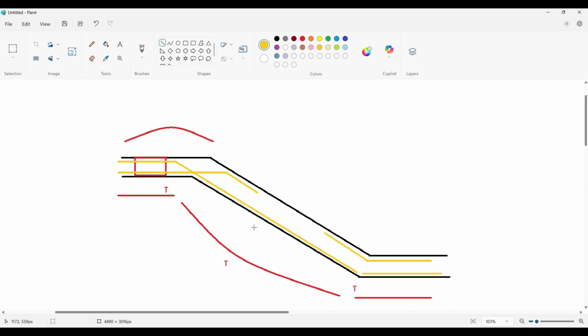Okay, now as I was saying, tension is at its max here, so we provide the tension zone over here. So we have main reinforcement over here. At the top we don't have any reinforcement, so at nearly 1/3 the distance, if I can just make it green, for example, at 1/3 distance we terminate the rebars. Okay, if the bending moments are quite high, we provide this reinforcement. If the bending moments are not high, we don't provide it.